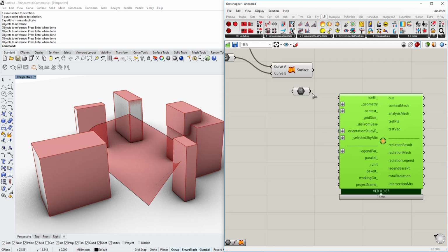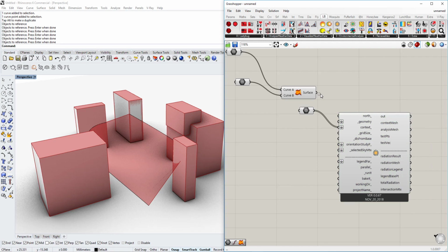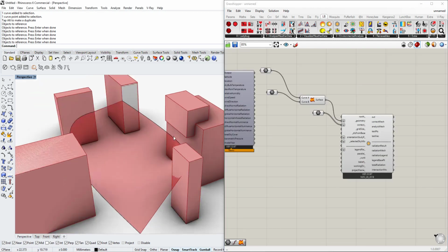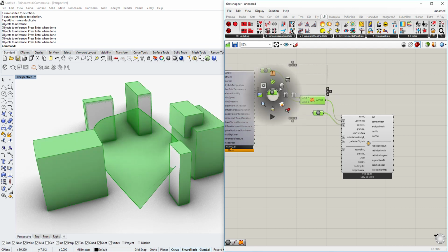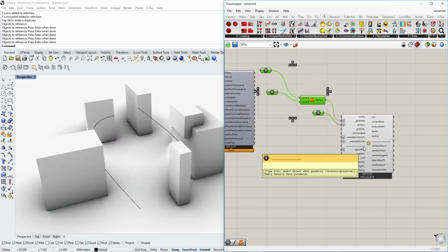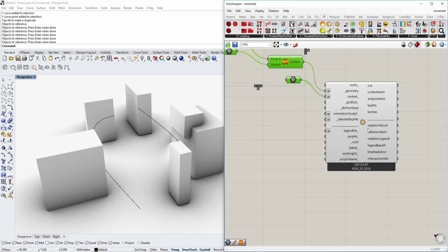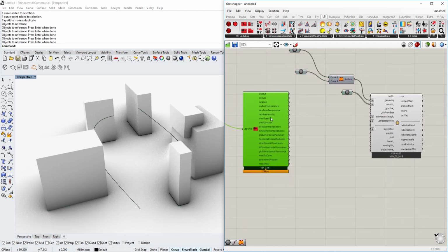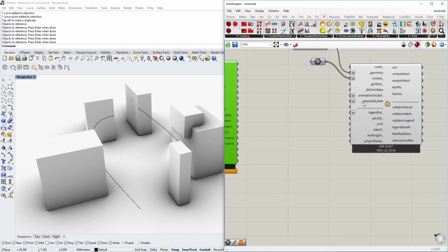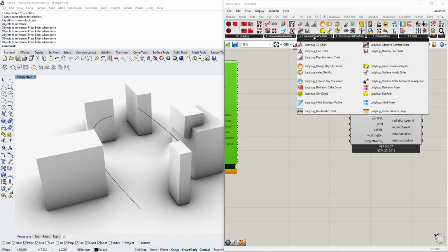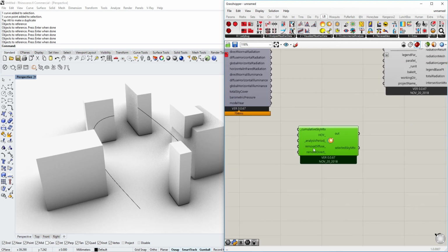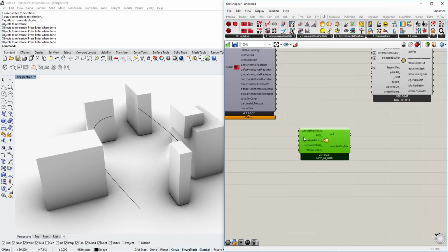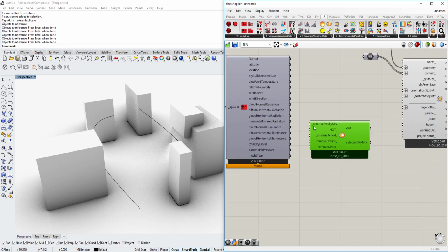What we'll need to do is, if we just put those things in here for now, nothing will really happen, because there is no data that Ladybug can use, since we don't have the EPW file connected to it. So what we need to do is create the selected sky matrix, and in order to do that we go to visualize weather data and select the sky matrix like this, and we would be able to get this from here.